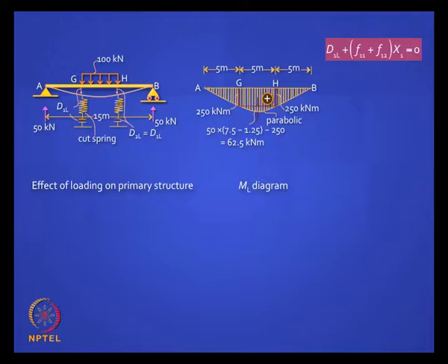So your first thing is you need the bending moment diagram when x1 and x2 are 0 in the primary structure. That is easy to do, okay. You have a UDL, so you have a parabola in the middle and you have two straight lines, and those areas are easy to compute.